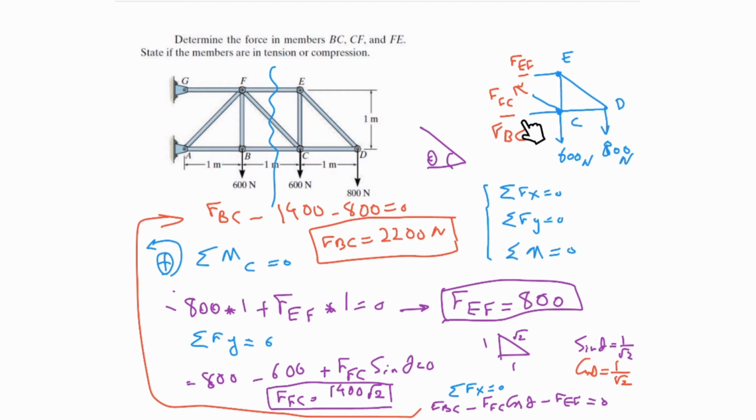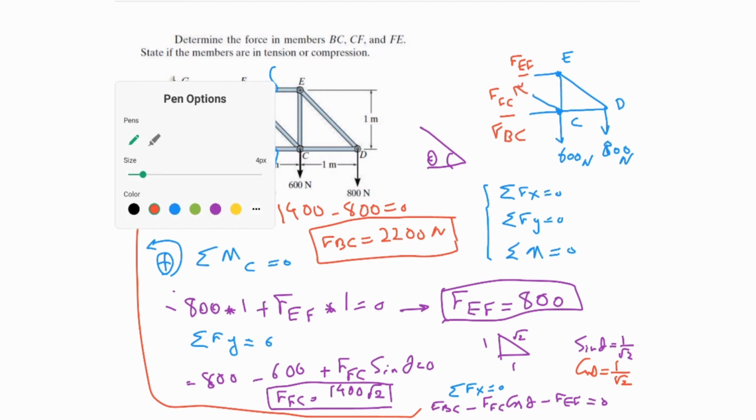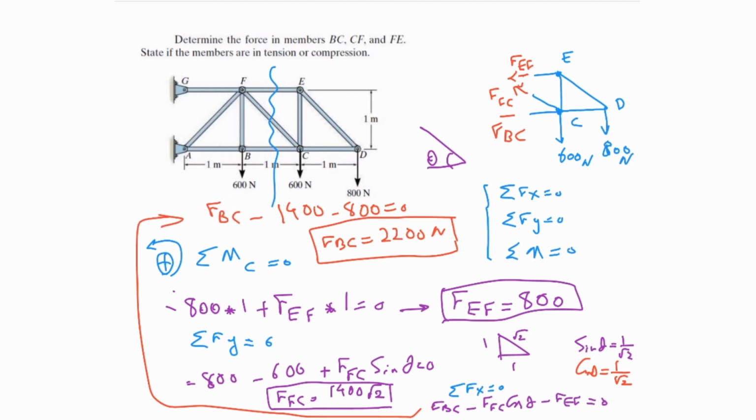That's one. If you take the moment around this, put a joint over here. These forces are not making any motion for it, because all of these three are crossing this point. But this force is starting to rotate this clockwise. This is the only force which is preventing that motion. We are in a static equilibrium condition, then this should be this.